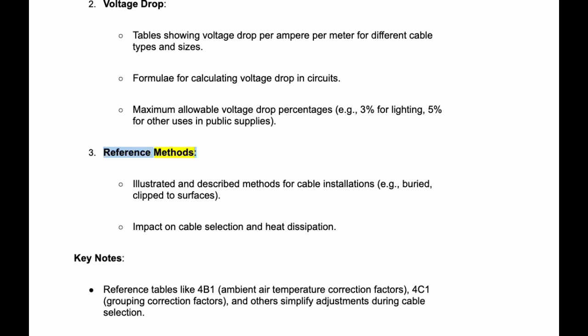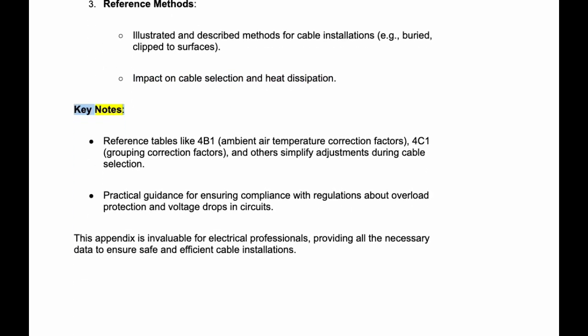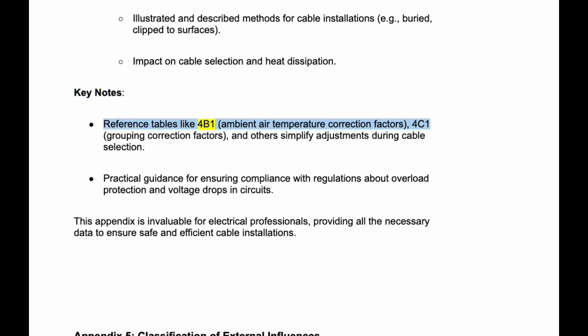Reference methods. Illustrated and described methods for cable installations, e.g. buried, clipped to surfaces. Impact on cable selection and heat dissipation. Keynotes. Reference tables like 4B1, ambient air temperature correction factors, 4C1 grouping correction factors, and others simplify adjustments during cable selection.